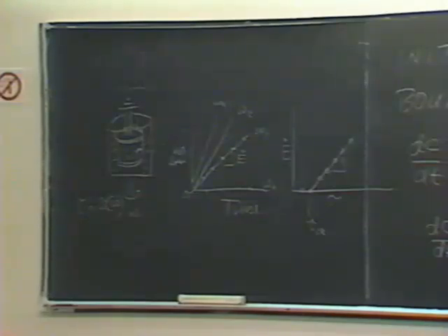It would seem that by using this technique of weighing the soil to determine how much soil is lost, you're also weighing some water, or not? The water in the soil. Entrained water in the soil, and as you lose more soil, you're also losing the ability to entrain more water. So I would think that actually measuring the change in sediment concentration in the water would be a more accurate way than weighing the difference in weight from the sample itself. You can calculate it from either the concentration or the other, but you have to know what the moisture content of the sample is. If you know the moisture content, you can calculate the solids loss.